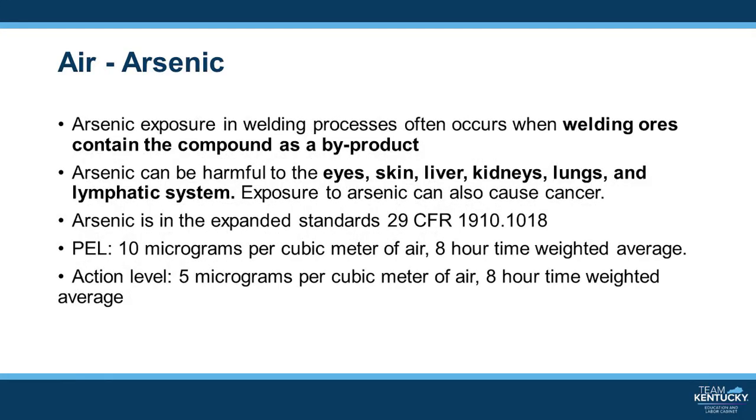Another possible health hazard in certain welding environments could be arsenic. When welding on aluminum, it may generate fumes that contain fluorine, arsenic, copper, silicon, and beryllium. Here we're talking about arsenic, and it can be harmful to the eyes, skin, liver, kidneys, lungs, and lymphatic system. Exposure to arsenic can also cause cancer.